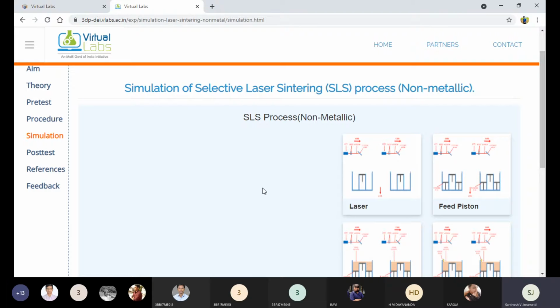The principle is that only the selective laser is used, so in that entire bed we need to select our area. What is our desired shape, what is in our mind, what the customer expects and demands, as per their intention and the 3D diagram, we need to create the 3D model in that powder bed. How is this 3D object created? Layer by layer. Each and every layer is scanned by the laser. Only the selected portion is scanned, hence that generates the 3D object, right?